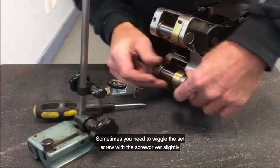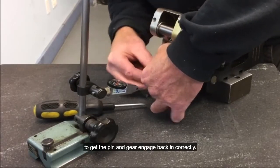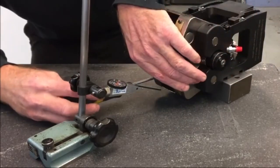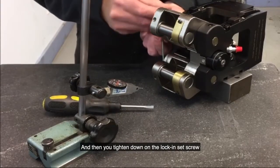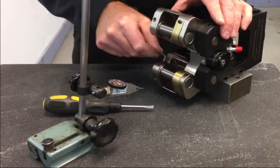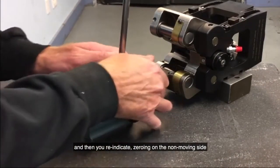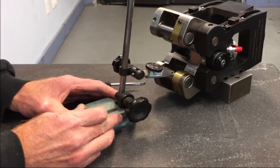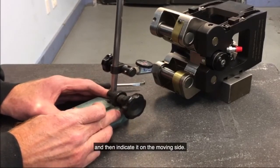Sometimes you need to wiggle the set screw with the screwdriver slightly to get the pin to re-engage correctly. That's what Jill's doing now. And then you tighten down on the locking set screw. And then you re-indicate, zeroing on the non-moving side. Then indicating over on the moving side.